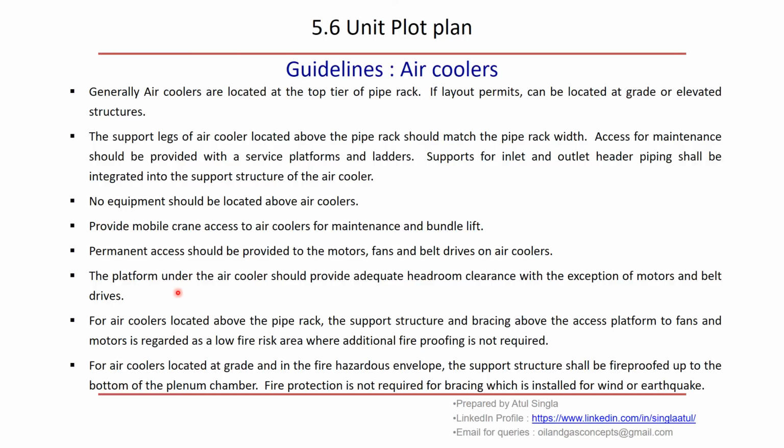The platform under the air cooler should provide adequate headroom. There should be headroom clearance below the motor, fan and belt drives, so that there is proper space for movement.